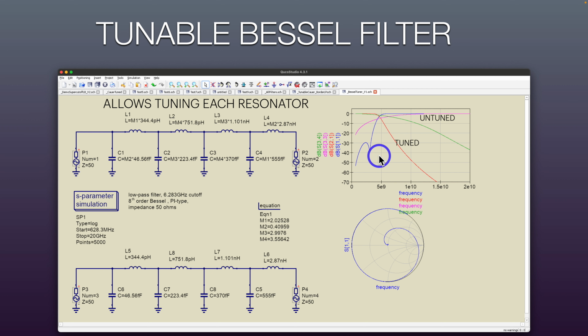So here we can see that we've gone from a fairly slow roll off of the filter performance to a fairly fast roll off of the filter performance. Are affecting this intersection as well. We're getting better performance out to a higher frequency. That may be at a trade-off for not getting as good a performance, like phase issues.